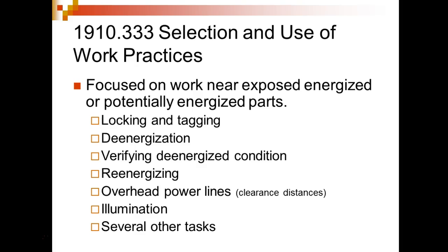I don't think 70E says that's legal. That's the reason I was curious. What I've read is it always says verify, and it usually says with a meter. If you could verify with a light... I'm pretty sure one of these little voltage detectors is legal. A voltage detector is just a unit that picks up AC induction and verifies if a voltage is there. I think that should be fine.